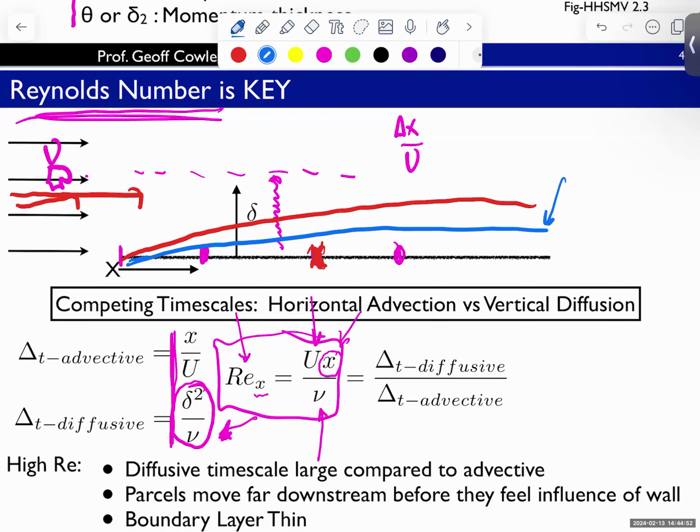For most of the work we'll be dealing with, I should also note here, the boundary layer grows with distance down the plate. So if this is the end of the plate or end of the boat, whatever it happens to be, the thickness of the boundary layer will be the maximum. And the relative thickness, meaning the thickness of the boundary layer divided by the length of the boat, or here the length of the plate, is only going to be a few percent, 1%, maybe 4%, just a single digit percent. When you look at this plate, I've probably drawn the boundary layer here more than a few percent. Maybe 6 or 7% is what I drew here. It's going to be relatively thin.